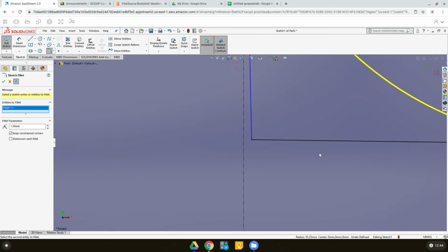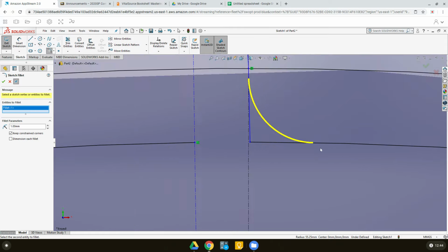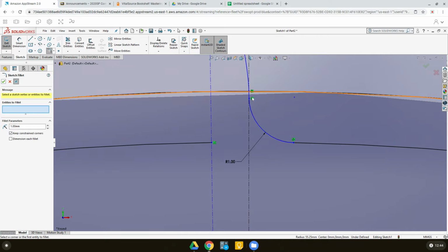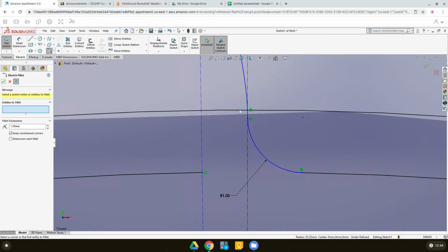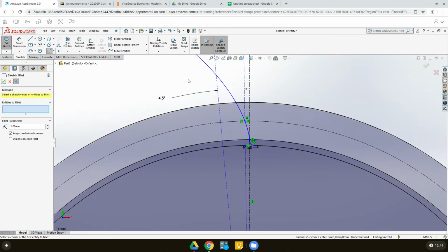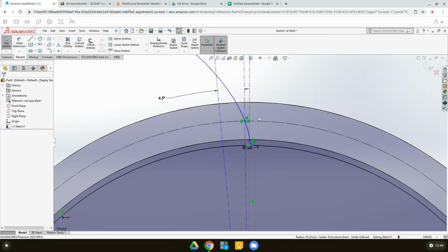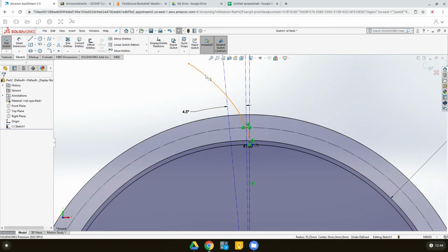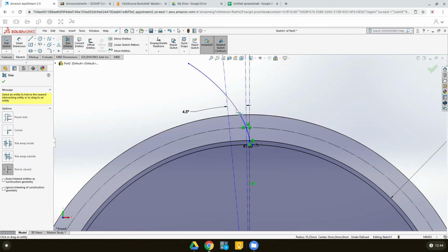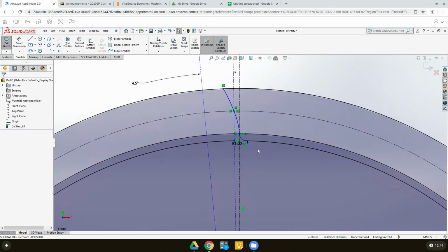And you see, where is the fillet? You will see if you zoom out, this yellow thing is the fillet. Everything looks okay. I'm going to click okay here. So far so good. Now we got this fillet. There is this part of this vertical line here, and then the involute profile of the gear tooth, all looking good. Also, you don't need the profile above the addendum circle, so you can chop that out as well. So trim entities, and you don't need this portion, you don't need that portion. Okay, so that's gone. And now we got a very good profile on one side.